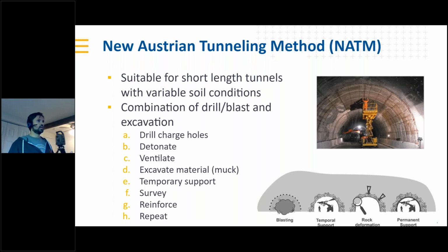And so this can be through a variety of means, but I'll go through the general process, which is starting by marking and drilling out the holes in the tunnel face for the charging, detonating those charges to break up the material, ventilating, so getting rid of all the dust and debris so it's safe for people, excavating that material, so that could be removing material by loader or other means, typically called mucking in the slang term. And then there's installing temporary support.